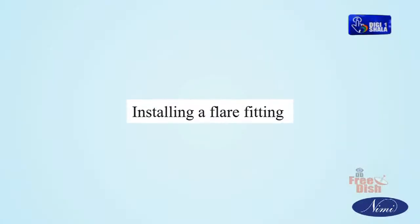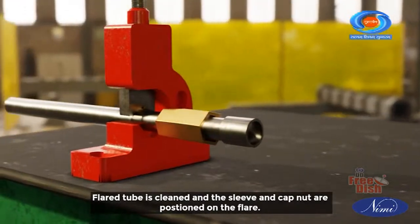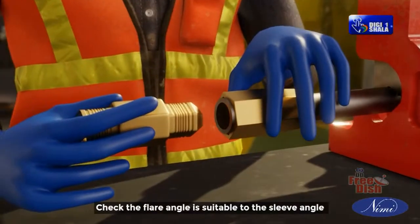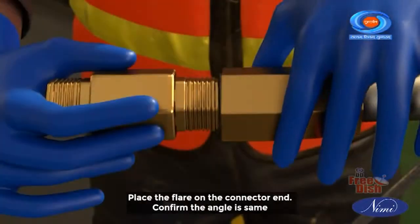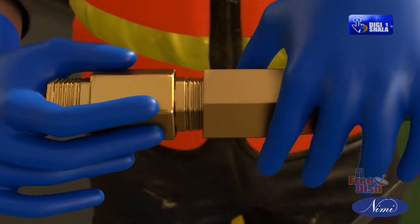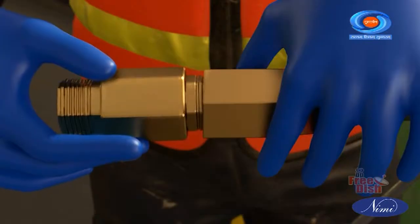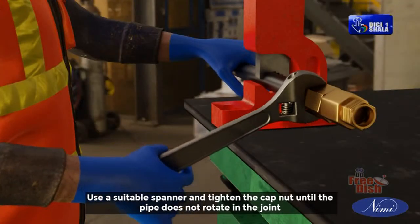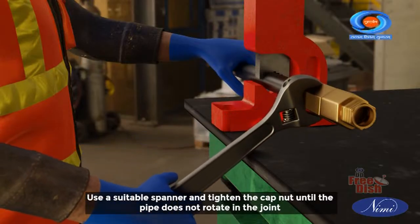Installing a flare fitting. The flared tube is cleaned and the sleeve and cap nut are positioned on the flare. Check that the flare angle is suitable to the sleeve angle. Place the flare on the connector end. Confirm the angle is the same. Screw the cap nut on the connector thread by hand. Use a suitable spanner and tighten the cap nut until the pipe does not rotate in the joint.